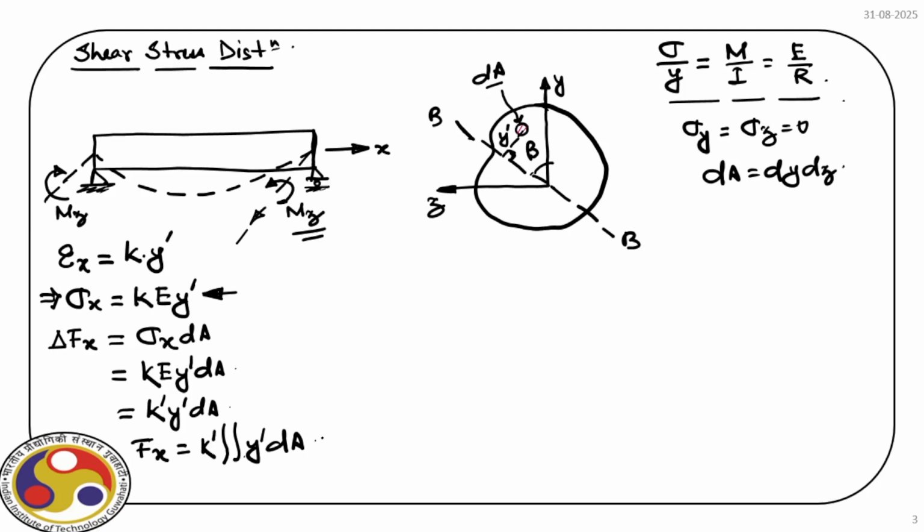To maintain equilibrium this has to be equal to 0. If you recall, for a rectangular section we developed the bending stress model: above the neutral axis you may have tension and below compression, or vice versa.